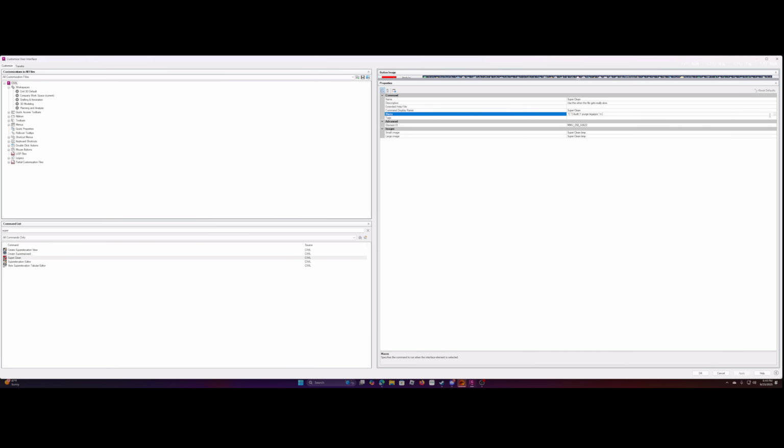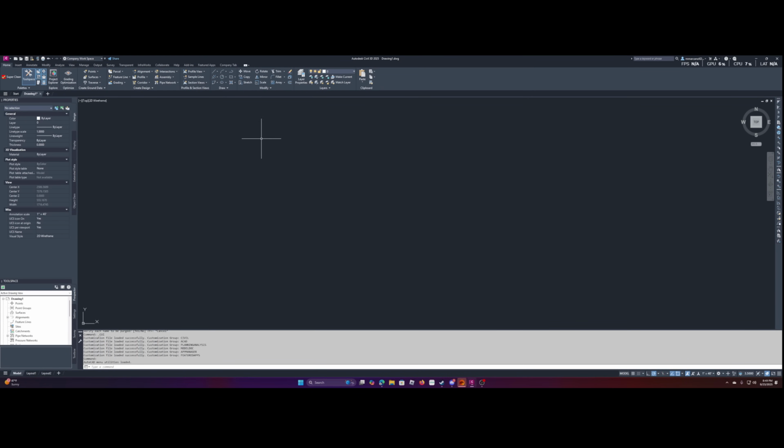And if you want to see a bigger image, you can hit these 3 dots at the right, and you get what's called your long string editor that you can use to see a little bit better. But this should be what it looks like. Audit, semicolon Y, semicolon -purge. And this here should not be a colon, but a semicolon. Oops. And then regapps, and then semicolon, asterisk, semicolon, no, semicolon. And so we'll hit OK. We'll hit apply. We'll hit OK. And so now, if we run it, it should run even with the purge.